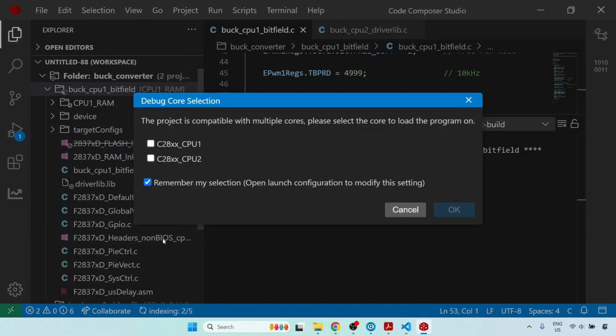So this sometimes has to do with the fact that when you change your directory structure, such as when you delete directories and move directories around, it stores the configuration JSON file in one of the directories and can't find it again. In such a case, when you restart Code Composer Studio, it rebuilds it again, and therefore it finds the JSON file. So all you have to do is close down your Code Composer Studio and restart it.